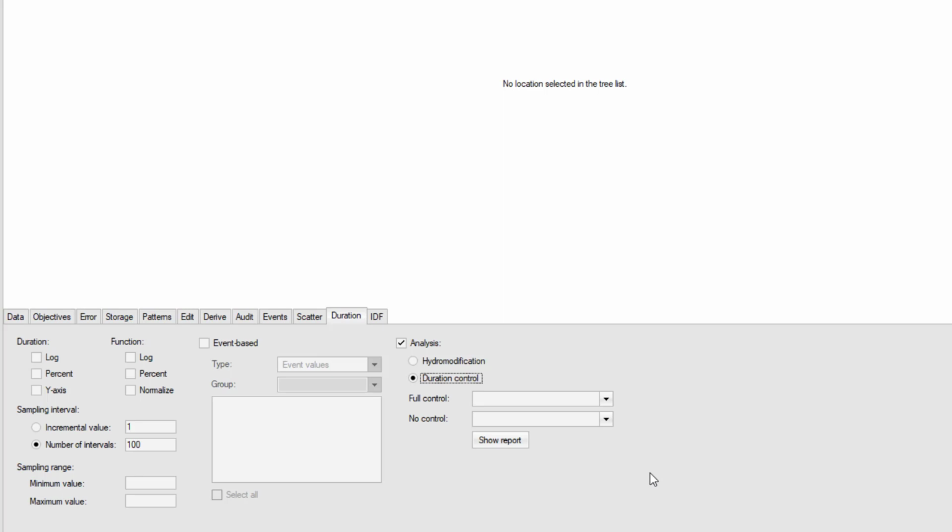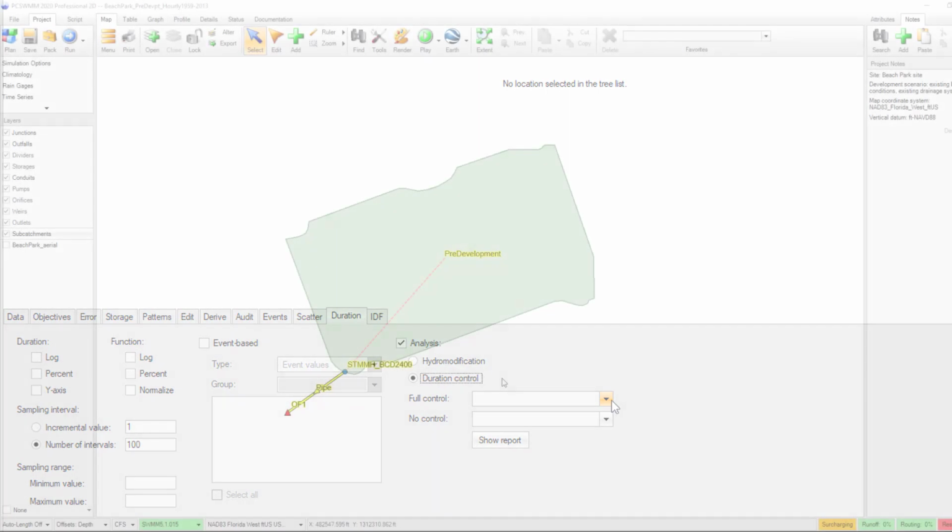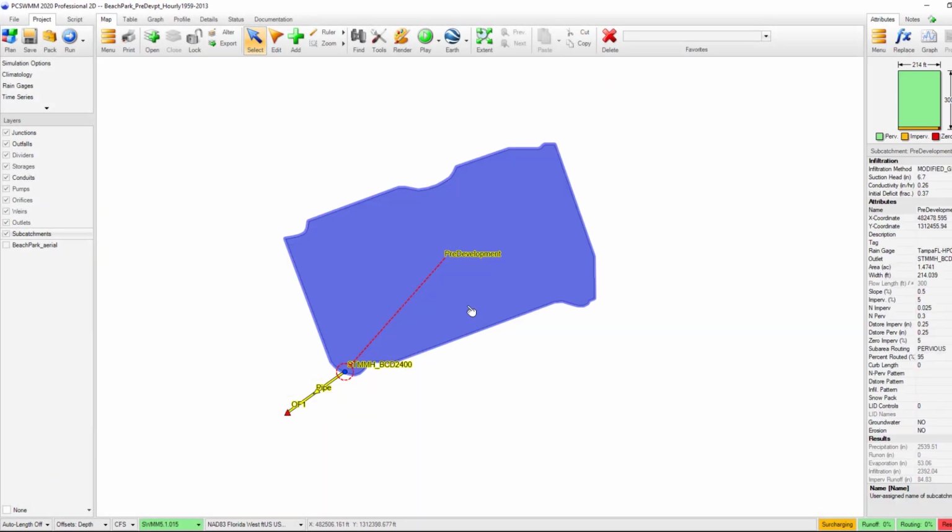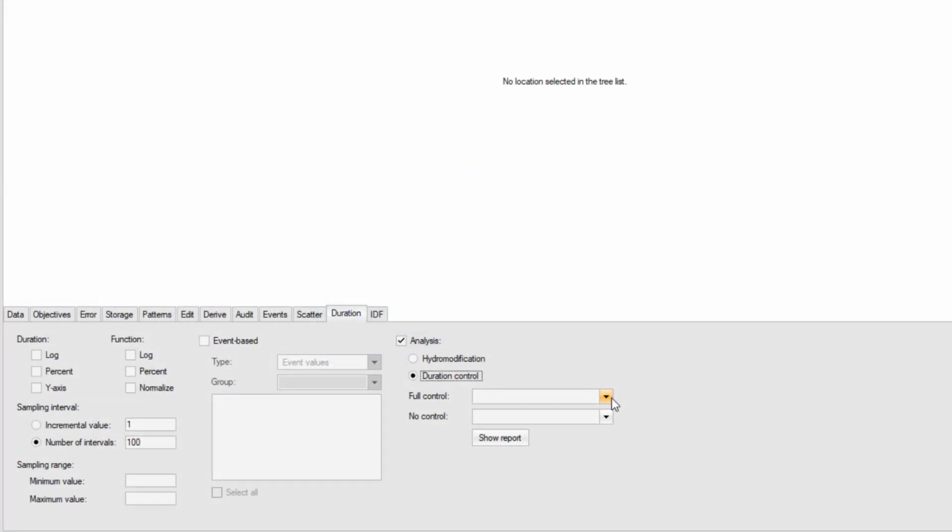The full control condition represents the most desirable performance curve for bracketing the upper end of the operating range. This typically represents natural hydrology conditions or a pre-development runoff response. A scenario that matches this flow duration curve would be the ideal performance that offers 100% control to the desired objective. The maximum level of control is capped at 100%, so that occurrences of overcontrol do not exaggerate the overall benefits when calculating the average control level.